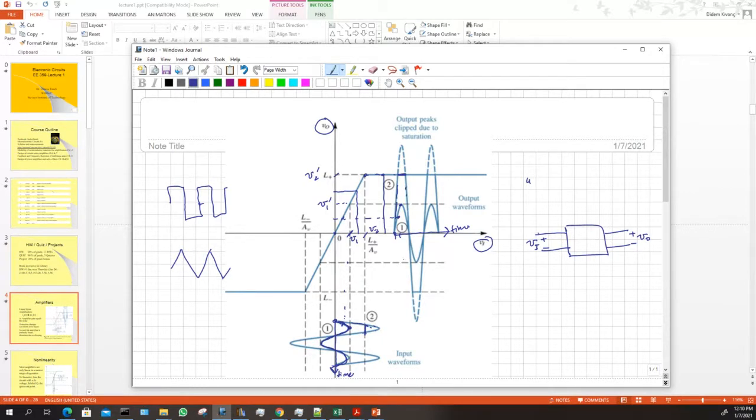Actually, sometimes we do this on purpose. This is a way to get a square wave from a cosine. You start out with a cosine wave, and then you clip the top really low down. You can see it looks like a square pulse wave. This is actually how the communications lab systems work. They do clipping. There's a cosine output, and you can see that because there's a little knob here, and then it connects, and there's a square wave output right there. So this is what they're doing between the cosine and the square wave. They're just clipping off the tops of the cosine, and they get a square wave.